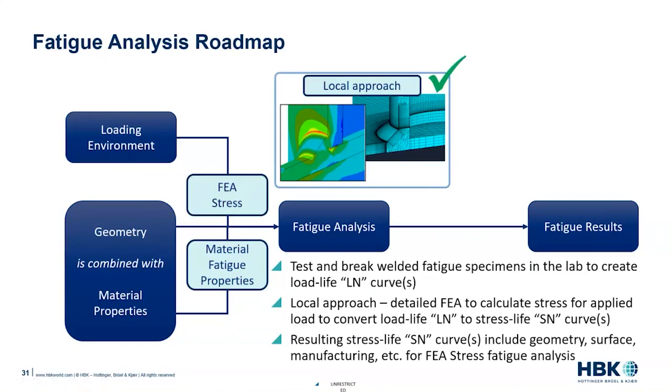So where we've got a detailed finite element analysis and we've got a local approach, then that's giving us a prediction of the stress that we can use, as the load life curve is converted to a stress life curve, so we can use that within the fatigue analysis.